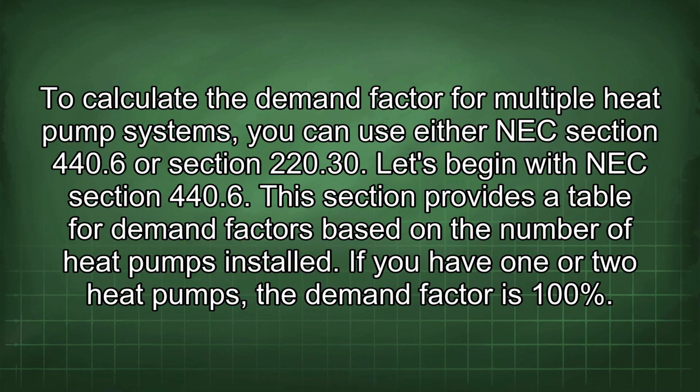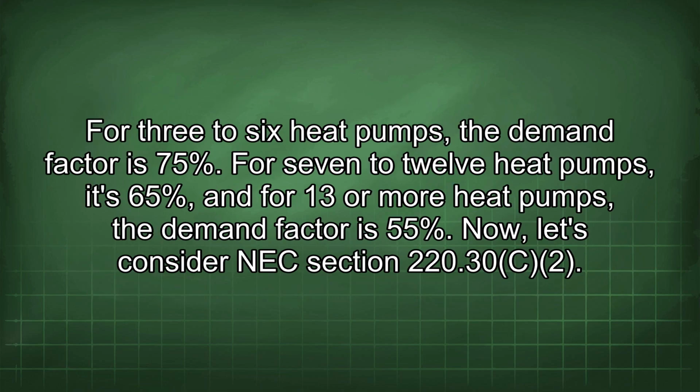If you have 1 or 2 heat pumps, the demand factor is 100%. For 3 to 6 heat pumps, the demand factor is 75%. For 7 to 12 heat pumps, it's 65%, and for 13 or more heat pumps, the demand factor is 55%.